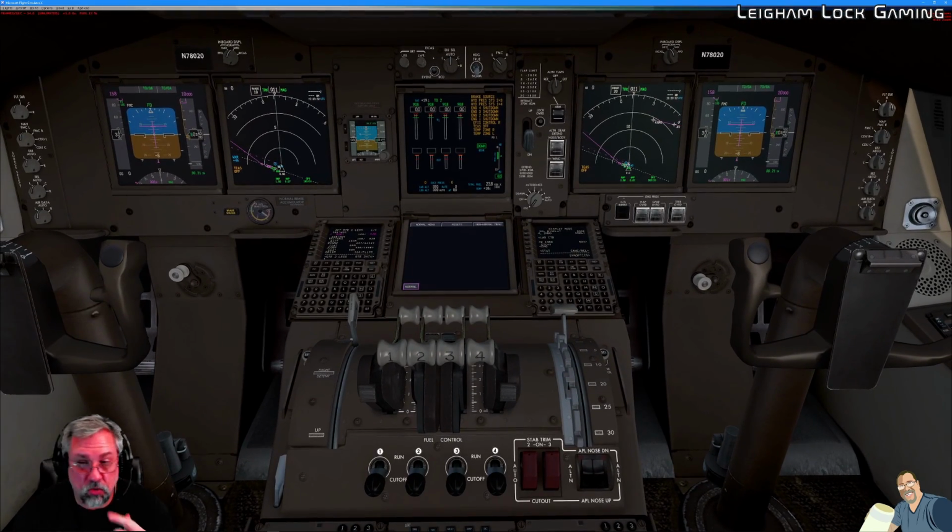It's this one. Here it is, controls. Perfect. So for controls, we want to make sure that the speed brake is in the down position, and it is. Our thrust controls are in the neutral or the idle position, and they are. Our flap is in the up position. This is verified. And again, recall these are the captain's pre-flight procedure checks.